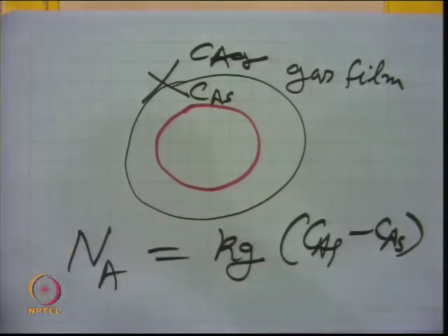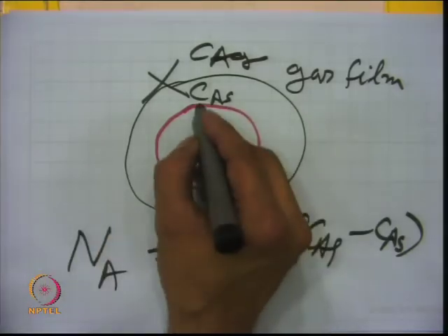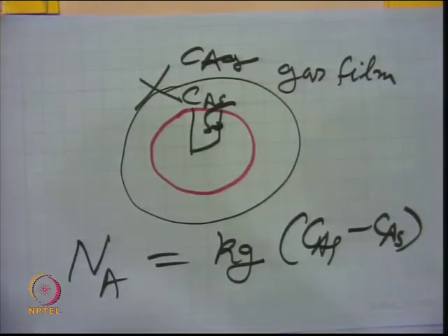And when you do the kinetics, this may hamper your overall rate of reaction. Same thing, the second parameter is your diffusion into the pore, and then we are talking about the third part, right. So, when you do the kinetics, you have to decide the conditions in such a way that this mass transfer should not affect the overall kinetics of the reaction, and that can be studied from hydrodynamics. You can confirm it from hydrodynamics, and there are some studies of the effect of mass transfer coefficient on the physical properties of the gas and the solid, and the velocity of the gas, right.